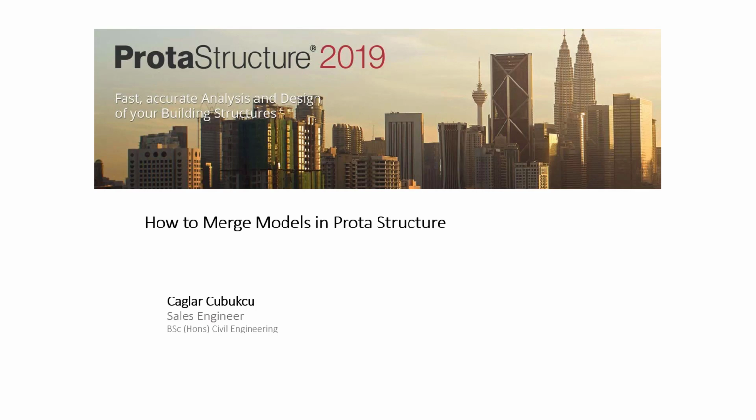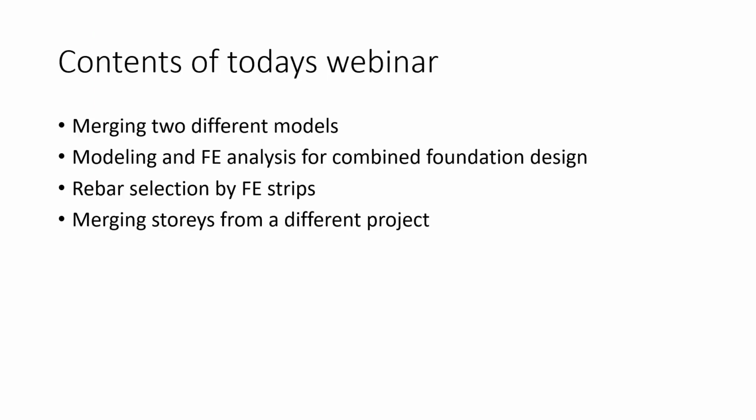Today, I'm going to talk about how to merge models in ProtaStructure. If we have a look at today's content, we'll be merging two different models. We'll model and analyze a combined foundation. We are going to do rebar design through strips, and we'll be merging stories from a different project.